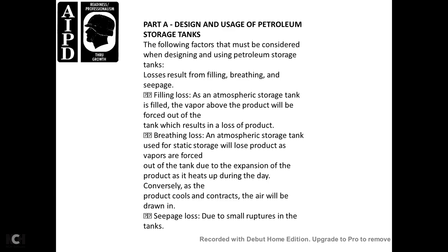Part A, designing and using a petroleum storage tank. The following factors must be considered when designing and using petroleum storage tanks. Losses result from filling, breathing, and seepage. Filling loss: when an atmospheric storage tank is filled, the vapor above the product will be forced out of the tank, with the result being a loss of the product.